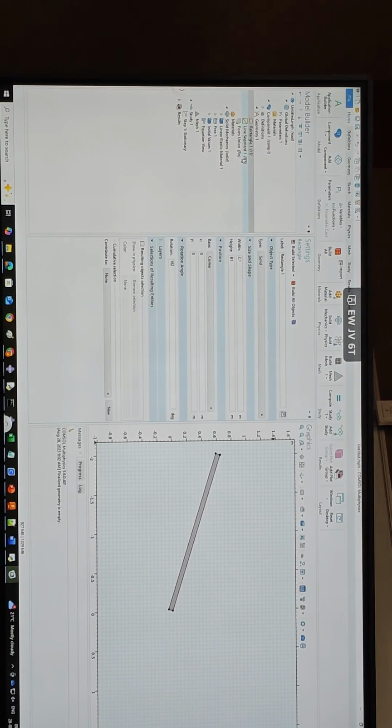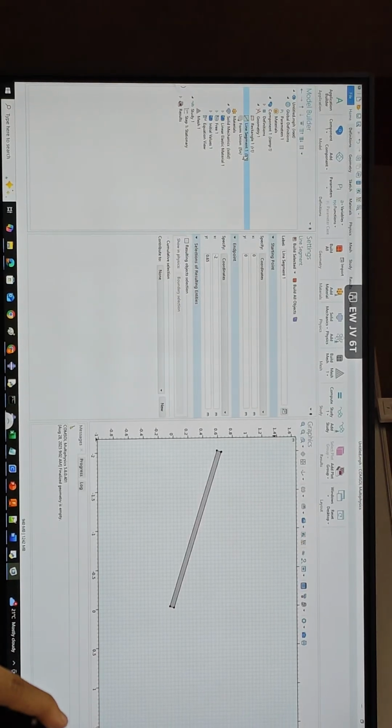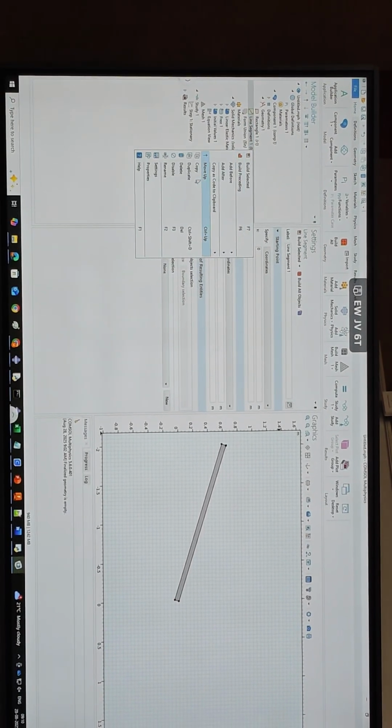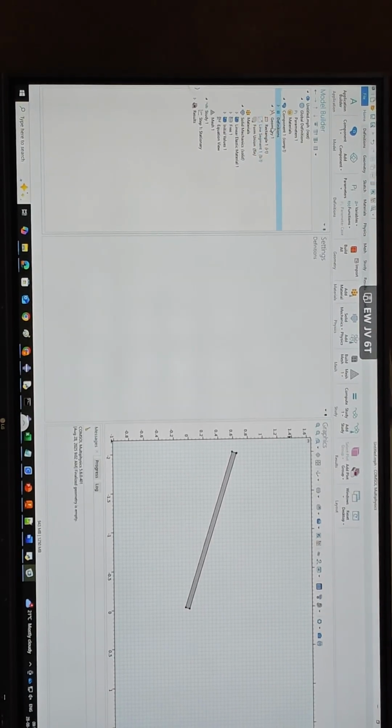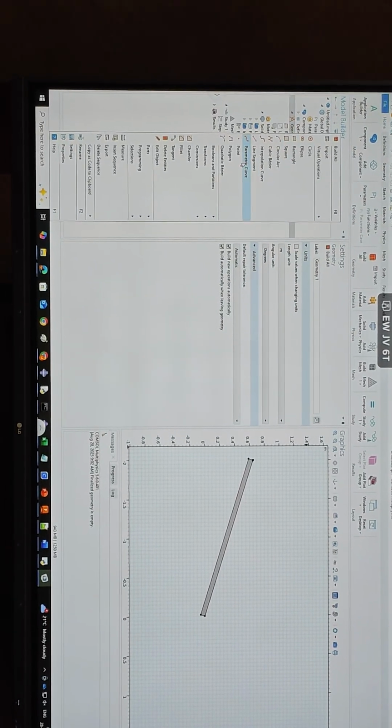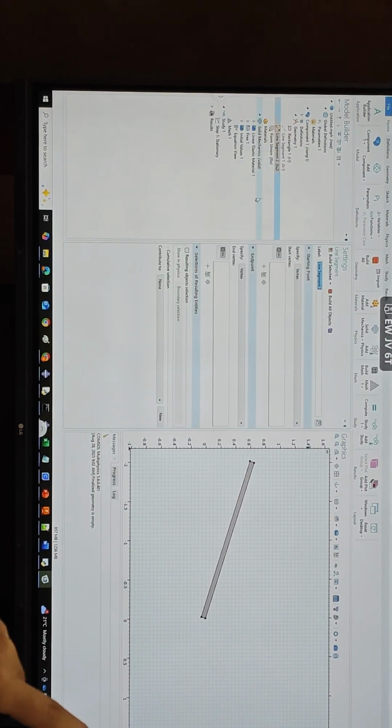So now I can go ahead here and disable this line segment, because we don't want this involved, because the mesh will have an issue if you have a line segment in between. So I'll disable it. So we have rectangle 1 done. Now we'll move to the next. So here I'll just start with the line segment first. So again, go back to coordinates.